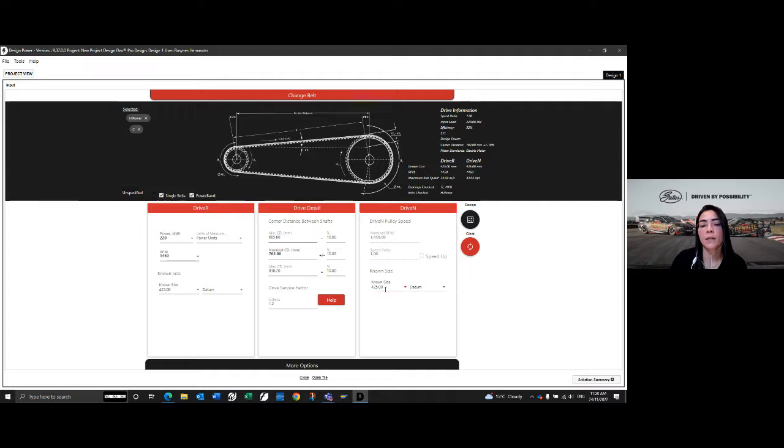So let's say you have only information for one pulley, and then you will be able to change the ratio here if you need it. And then you need to have the center distance, which is given by the customer. So it's 832. And then the system will automatically calculate the max and minimum tolerance between that. So max and min it will be if you have, for example, the flexibility to adjust your center distance. So this is what it will consider on the calculation.